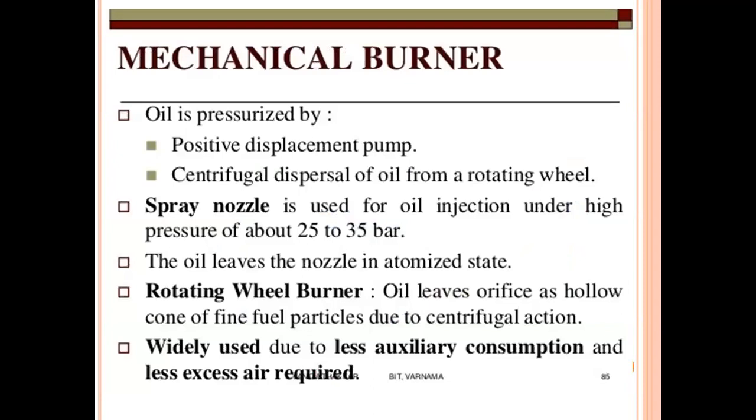Mechanical burner. Oil is pressurized by a positive displacement pump. Centrifugal disperser of oil from a rotating wheel. A spray nozzle is used for oil injection under high pressure of about 25 to 35 bar. The oil leaves the nozzle in an atomized state.